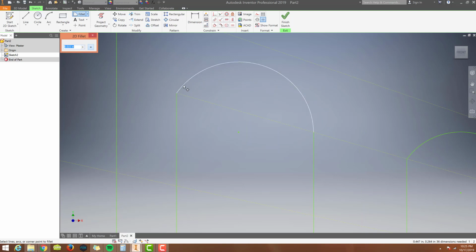And then I'm going to click on the top line with that fillet tool active. And then if I hover over the bottom line, you should see that it will start to arc, okay? I'm not going to click on it just yet because while that's a decent fillet, it's not enough. So I'm going to make it just a little bit bigger now that I know it works. So I'll do 0.04 and I'll hover. It's too much because it doesn't show. 0.03 looks just right, so I'll click on it now, okay? So if your fillet does not show, it means it's too much fillet, or it's too little. You just have to get the right amount.